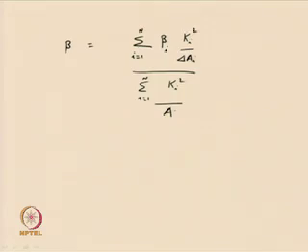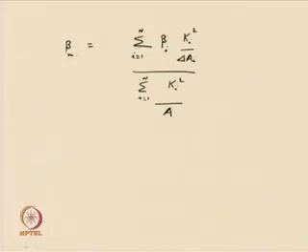So, like this you can obtain your energy and momentum correction factors for the entire compound section, and you can subsequently incorporate them while computing the velocity head, momentum fluxes, whatever fluxes or relations you want to use. You need to appropriately incorporate them.